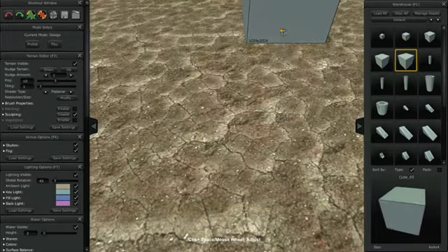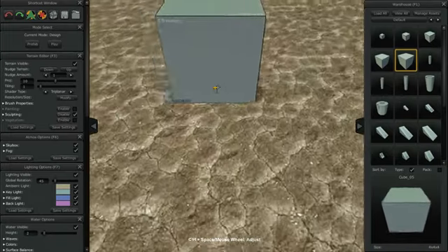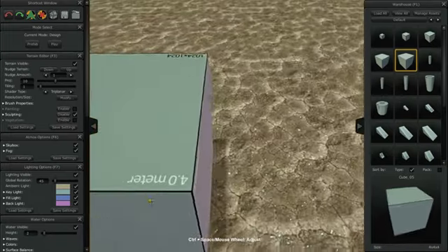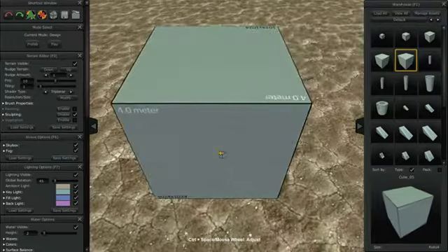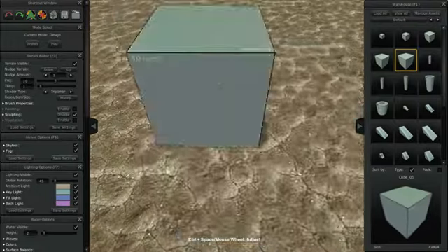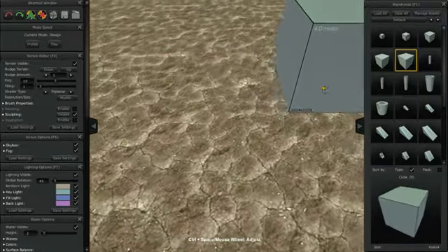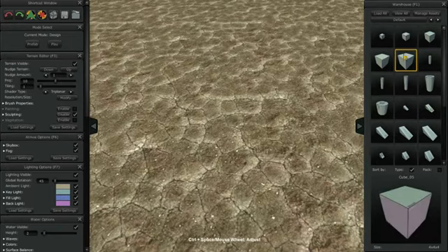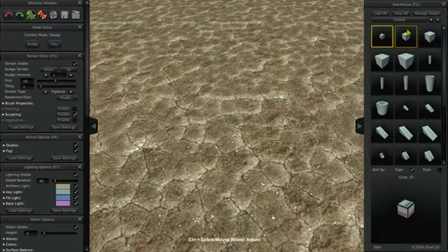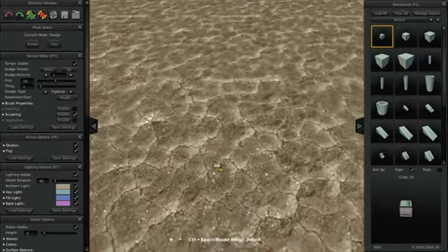By just floating the object over the terrain and pressing the F key on your keyboard, the camera will move and adjust to fit the volume of that object to the viewport. By using the WASD keys on your keyboard, you can also navigate the viewport camera. By pressing and/or holding down the WASD keys, you can move around the workspace.